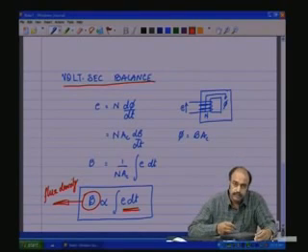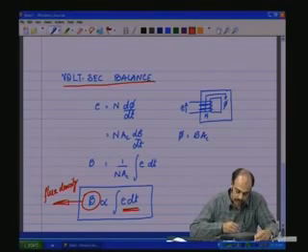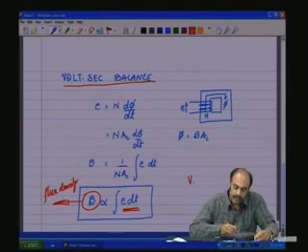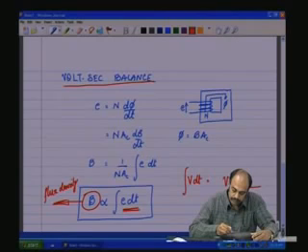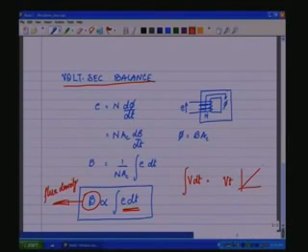If, for example, we have E as a constant of amplitude V, then integral of V dt is going to be V into T, and this has a ramp waveform, and this keeps on increasing beyond a particular value where we have B sat. Beyond that particular value, the core will saturate and it loses its magnetic properties.